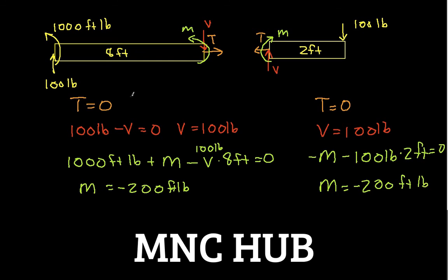So what we've shown here is how to find these forces, and it also turns out that it doesn't matter which free body diagram you use after you've made your cut. You'll get the same answer if you use the one on the left of the cut as you will when you use the one on the right of the cut.